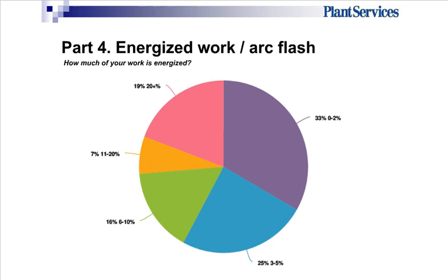So one easy way to do that is to activate the panel but have an IR window installed so that you're able to use a thermal camera to detect any hotspots in any conductors or connections that you happen to see. Obviously, a hotspot's going to happen if you have excessive resistance with a loose connection because the current increases and that creates heat. So this definitely represents that a lot of work is done in front of that arc flash zone or in an active panel. And ultimately, you want to use tools and techniques that keep you away from those active conductors as much as possible.